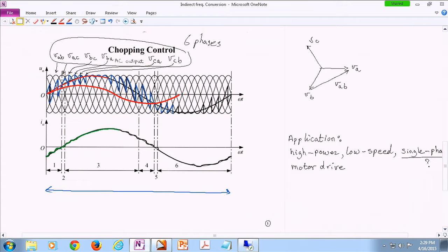If your frequency gets too close to the line frequency, then your jumps are going to be less frequent but more severe. So the resolution gets bad, basically. Ideally, you want a very low frequency signal, something that takes forever to ramp up. So the lower the frequency, the better the resolution is.